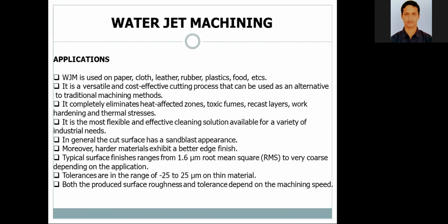If the thickness is higher, the lower part cannot be cut, and there will be an inclination, or the surface will be blurry and it cannot cut easily. Also, the water reduces its pressure easily. So I don't find any fixed limitation for thickness.